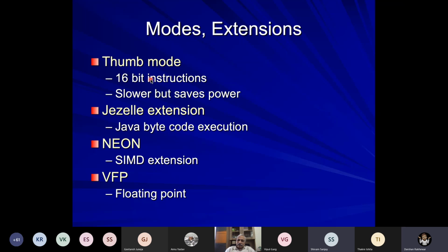The instructions are represented in 16 bits. More or less similar instruction set is there, but with some restriction. For example, you may not have a 3 address structure. Instead of saying add R1, R2, R3, you may say add R1, R2, which means that you perform addition of R1, R2 and put back result in R1. So one register acts as one of the operands and the destination of the result, as we have seen in 2 address instructions.